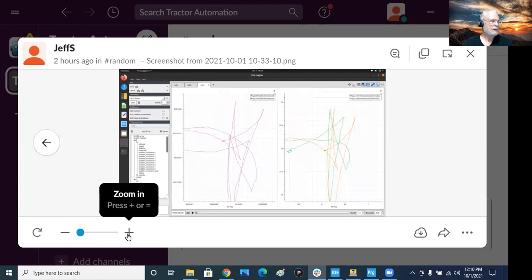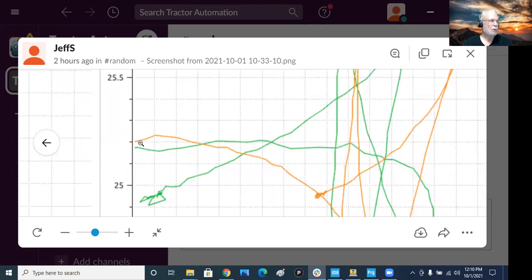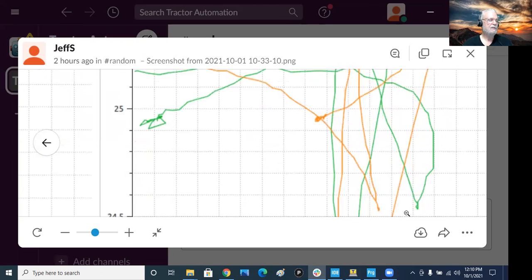And maybe if I play with it a little more today, I'll get to the point where, let's look at this one again. So on this one, theoretically, this orange line and the green line should be right on top of each other, either follow this path or follow this path, whichever, by the time I'm done. That's the goal. And if I can get the two antennas to report the same value, then I can say, what's the front antenna to base link? In which case, then the front antenna or the back antenna will be both on top of base link. The results will be on top of base link, and then all three of those values should line up as I drive around. So that's my goal at this point, is to do that.